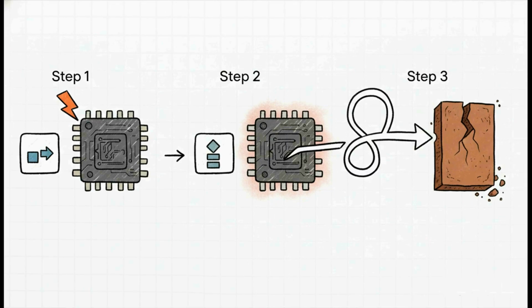This is how bad it can get. That tiny voltage droop can cause the CPU to misread a single bit in an instruction. Suddenly, a simple move instruction gets misinterpreted as a pop instruction. This could make your program counter jump to a totally random address it just pulled off the stack. And if that address happens to land inside your firmware's flash update routine, you've just accidentally told your device to erase itself. Congratulations, your product is now a paperweight. And it all started with a tiny, invisible power glitch.